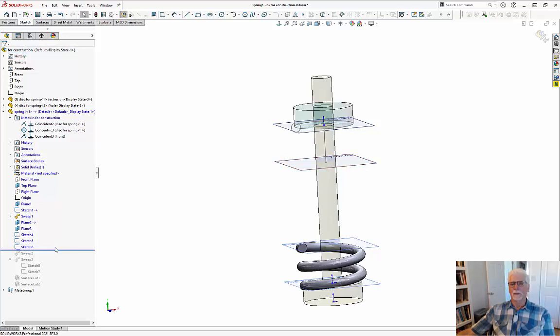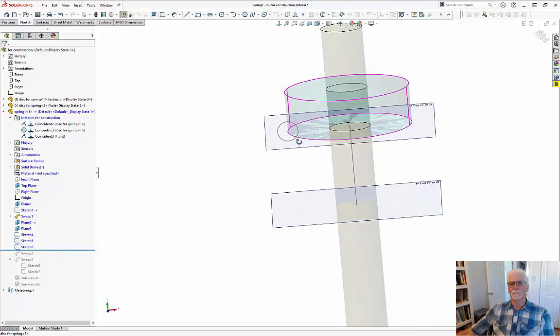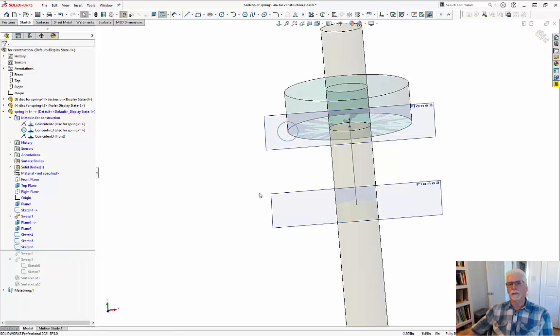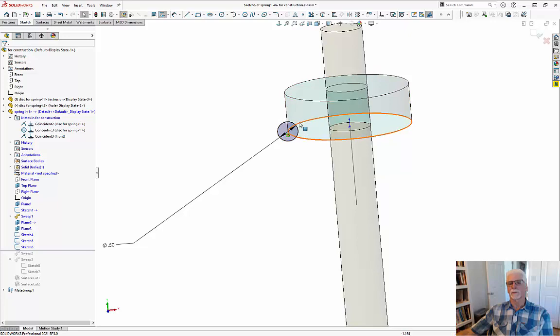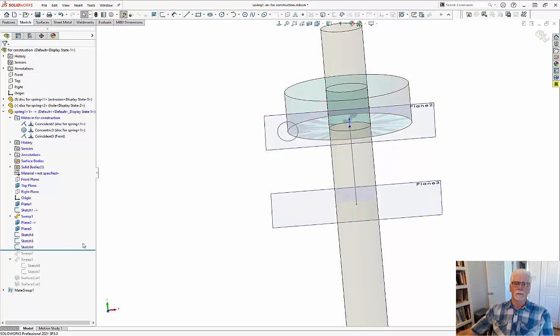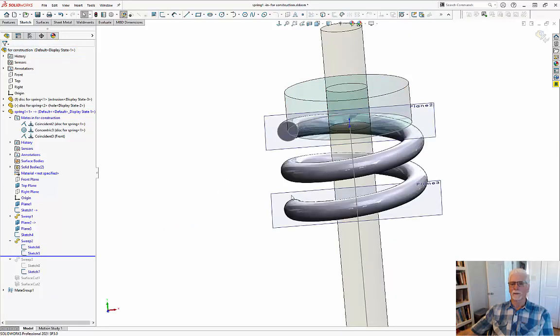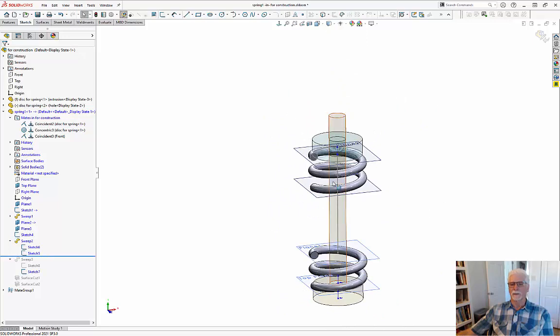And then I did that same trick with the circle, and I pierced that sketch I just talked about that we converted, and it's the same setup. I guess we can edit that and show it to you real quick. So we got the circle, and that pierce point is this circular sketch here. Okay, and so now we've got everything we need to make that second sweep. And that second sweep was done just the way the first sweep was: 2 revolutions and ended it right there.